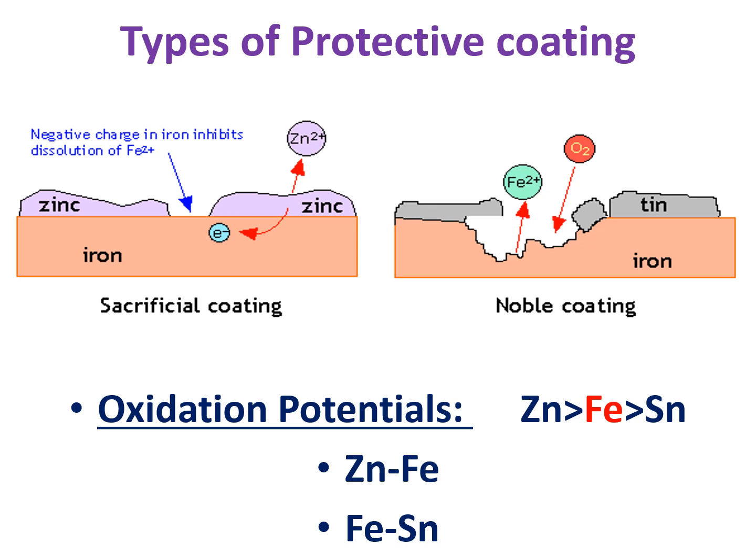For example, if you take iron metal, in the galvanic series, before iron there are metals having higher oxidation potential values, and after iron there are metals having lower oxidation potential. For example, zinc, magnesium, and lead have higher oxidation potential than iron. They act as anodes compared to iron. Tin, copper, and silver (Ag) act as cathodic metals compared to iron. So in zinc and iron, zinc acts as an anode and iron acts as a cathode. In tin and iron, iron acts as an anode and tin acts as a cathode.